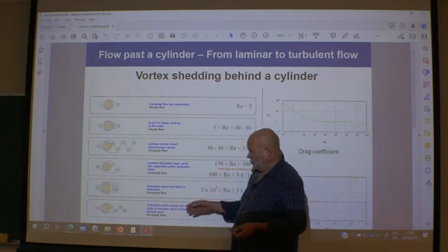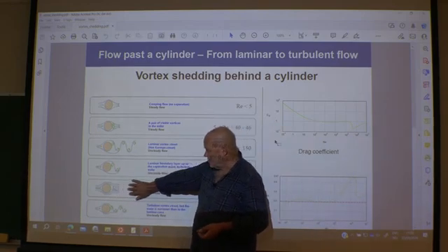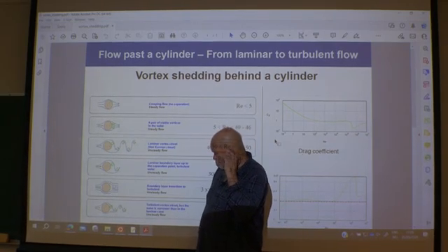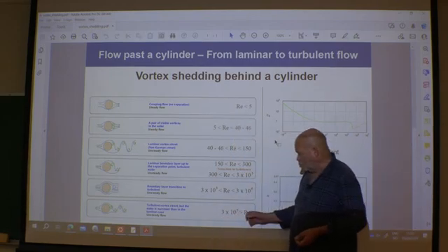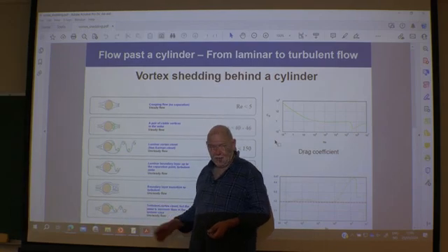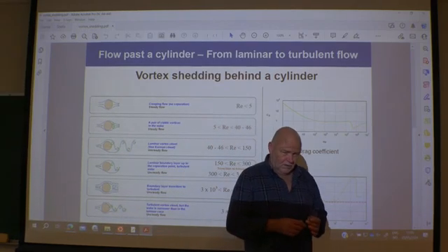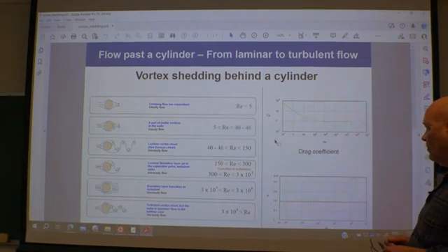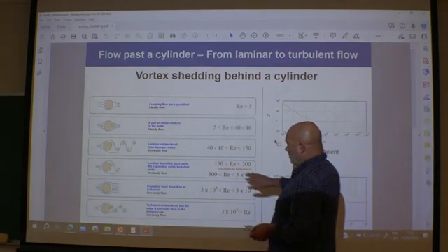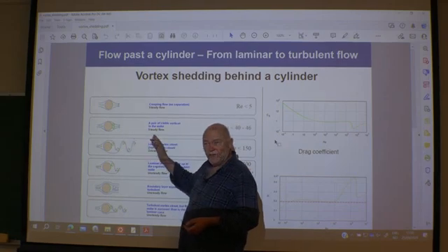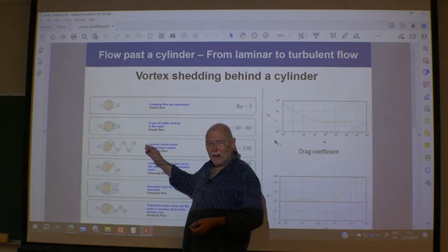Here you will have a quite unstructured flow behind the cylinder, but with an even higher Reynolds number, you will actually get this structured pattern again. Here you have to be careful what is turbulence and what is laminar flow. This one, nice, beautiful vortices that will change in time. This is not turbulence. This is laminar structures.